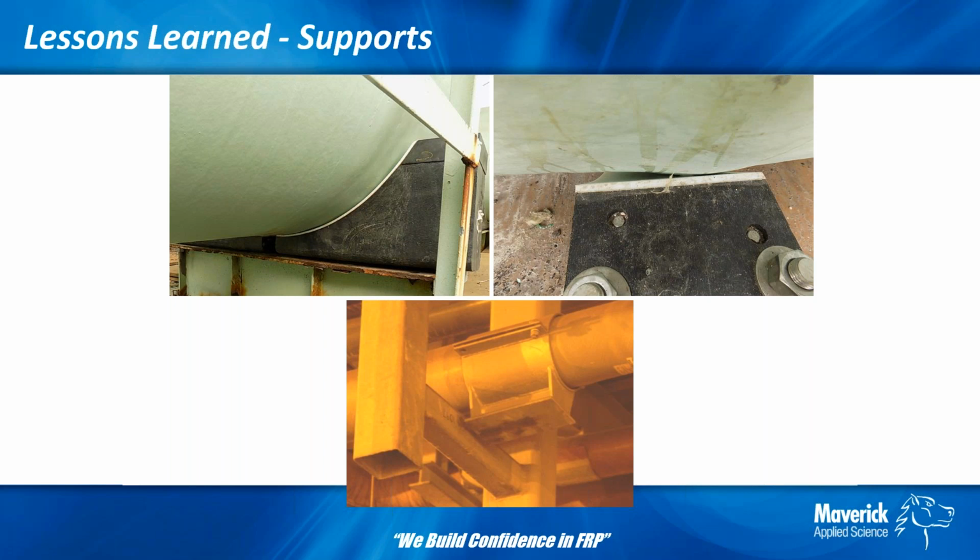It's when we see leaks and failures, it's in the joints, it's in the T's, the elbows, the fittings, but to a great extent, it's in the joints. So we don't want to put the joints at a high stress point.